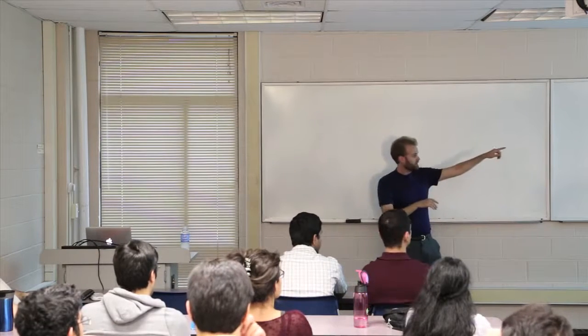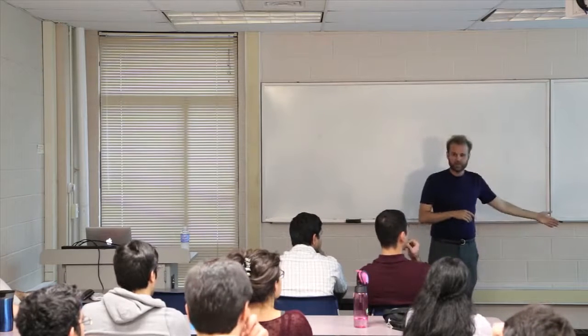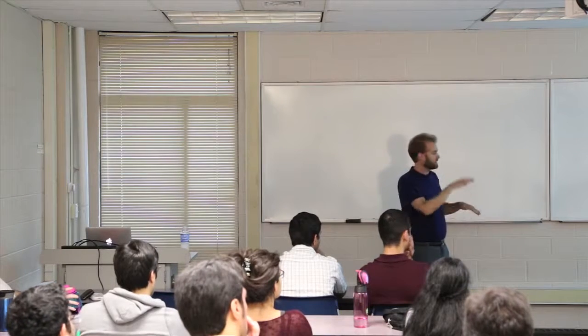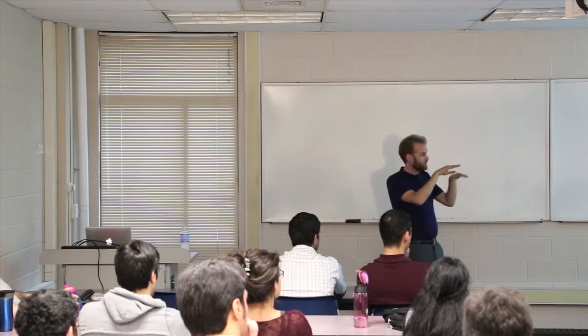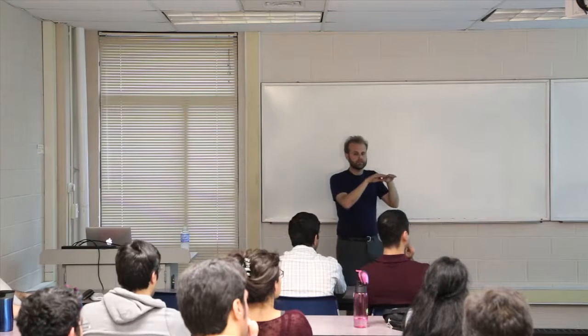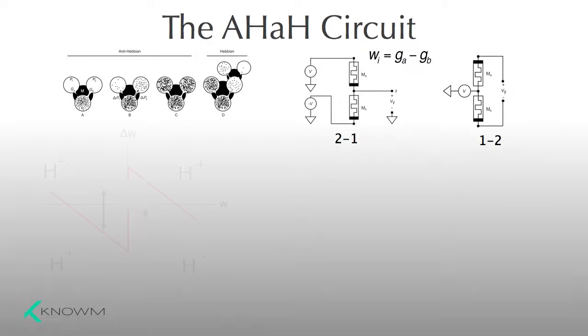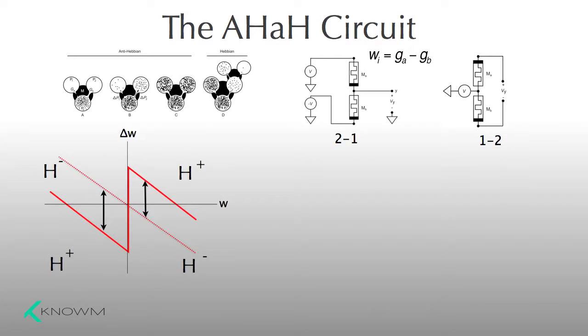So if you apply, say, plus V on top, minus V on bottom, and you repeatedly drive this thing, it'll go to 0 volts. It'll go to 50-50. It'll go to an indeterminate state. Now, if you reward one of these memristors, they're competing for energy dissipation. So if you reward one of them, you can drive the system the other way. Naturally, they're just going to go to 0, but if you give one of them a little burst, you can make it more positive or more negative, whatever you want.